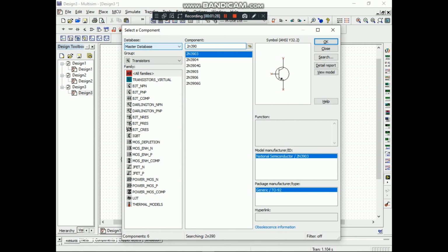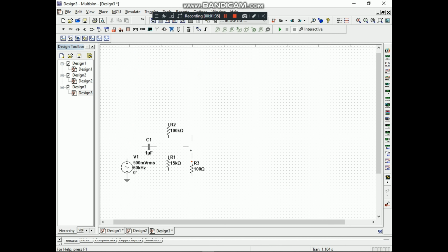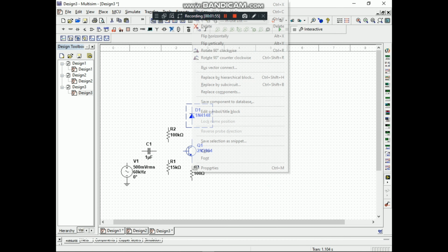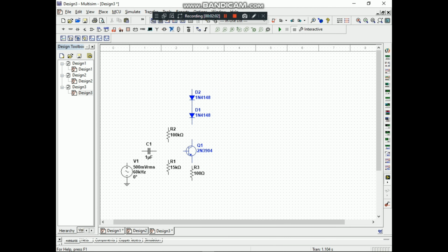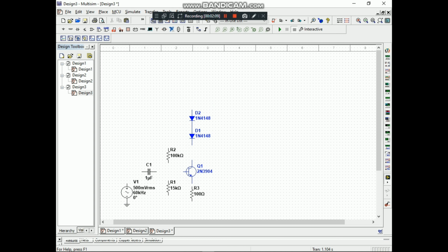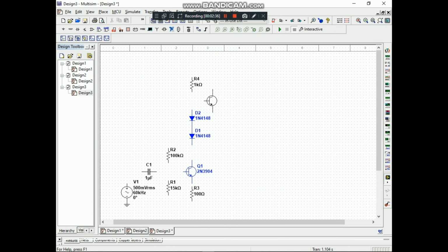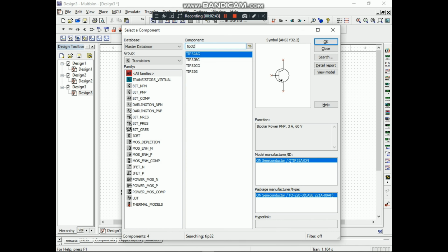The first transistor that will be used will act as a current source that sets up the required DC biasing current flowing from the diodes. Then, a pair of complementary NPN and PNP transistors is used. We also implemented input coupling capacitors and an output coupling capacitor.